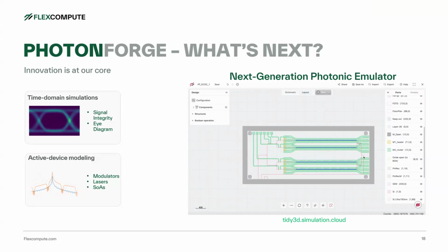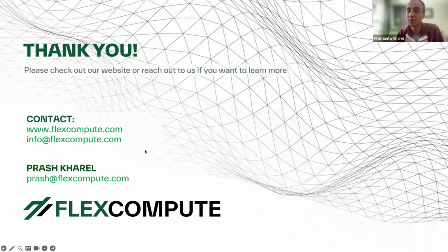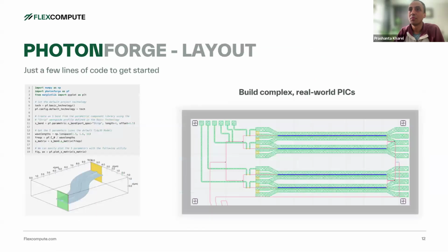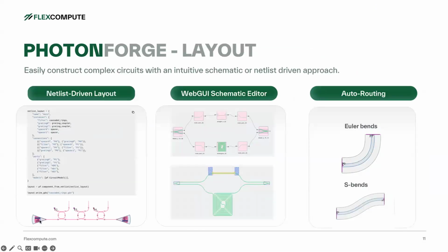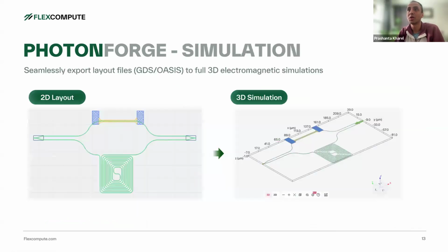I see. And this is at the chip level, right? There's no package level. Like you're not modeling the coupling from the fiber into your chip, right? You can. That model can just be an FDTD model. So you can launch, maybe I'll show, there's an image here. You see this image with the grating coupler here? Oh, okay, I see. So you can have a model for this grating coupler or whatever edge coupler, and you'll have a model for how the coupling losses and all that stuff depend. If you had a wire bond, if you could do electrical simulation, you can build a model for that. So it's a pretty general concept.